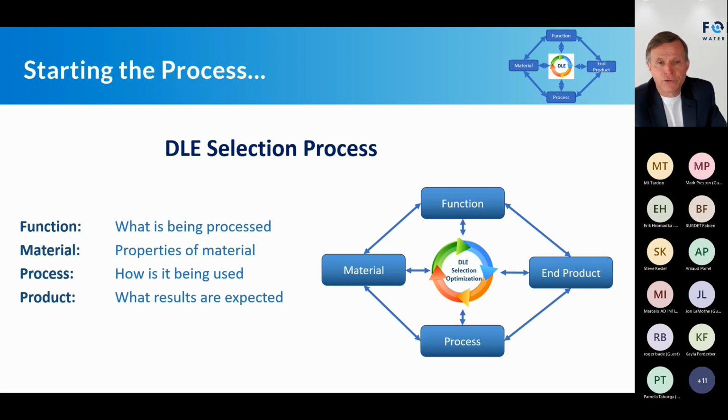Process: how is it being used? How am I going to be processing? How am I loading the brine? And how am I going to process it? Temperatures, and then lastly, the product. What am I expecting? What is the quality I'm trying to get? What is the finished product? Is it lithium chloride, lithium hydroxide, lithium carbonate? And what's the quality I'm trying to get out of this? Am I going to create a battery grade formulation and push that up, or maybe I'm just going to produce lithium chloride and pass it over to someone else to do the processing, the refining.